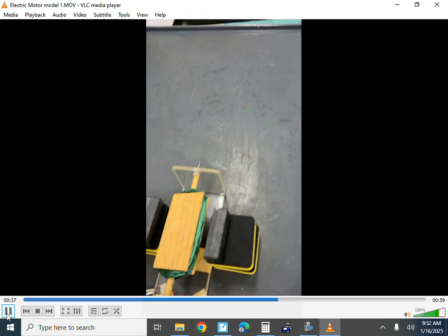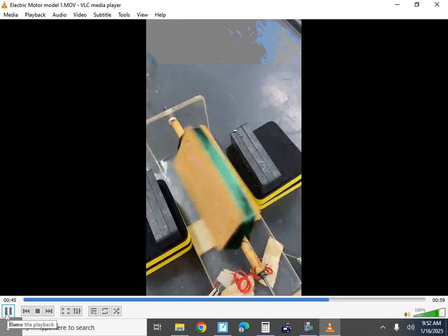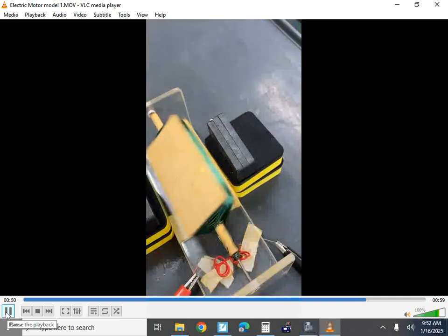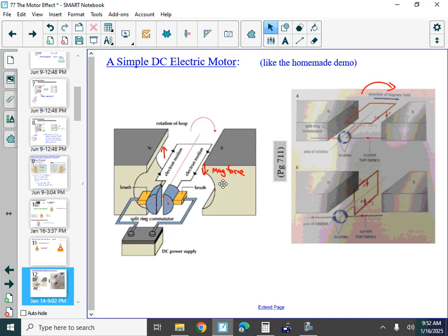Push down, and so when I turn the electricity on, I can give it a little kick, and it runs in the direction that I described. And I made the magnets closer, and it is not magic, it's just a motor. So that design is essentially this, right? You've got a big old set of loops of wire and you've got the 2 sides. If you had a semicircle for contact, you'd have the magnetic force happening for longer, and it would make it a stronger motor. But it works the way it is.